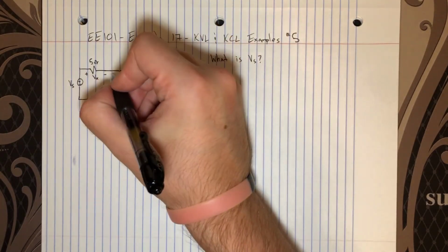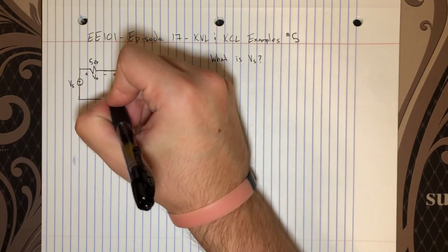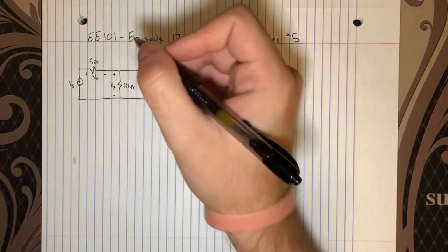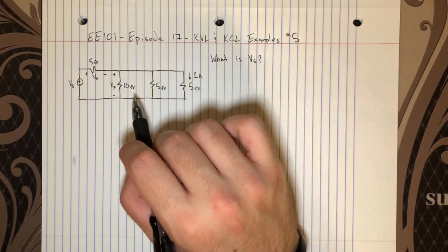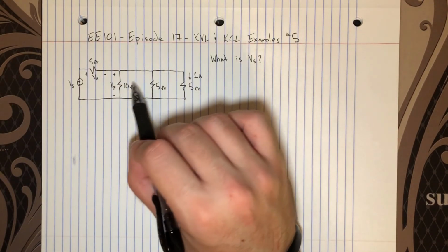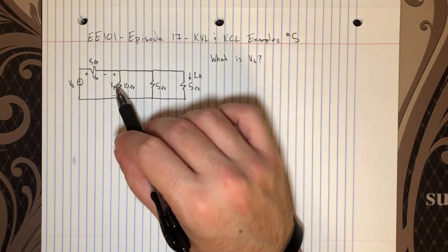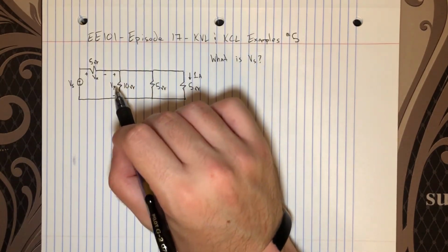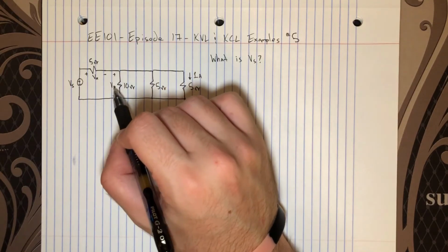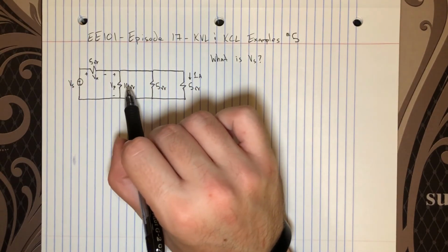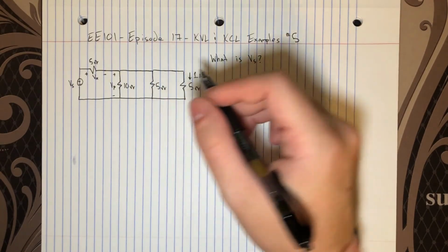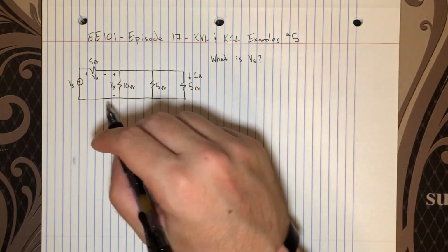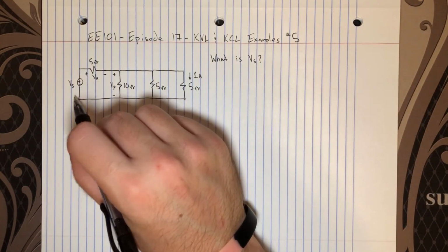And then I'm going to say there's a voltage here, this plus minus, and I'm going to call this Vp, P for parallel, because I'm recognizing that these 3 resistors are all going to share the same voltage. So I only have to label one place here, and I've covered the voltage for all 3 of these resistors. Okay, so the next thing is let's write out this KVL.